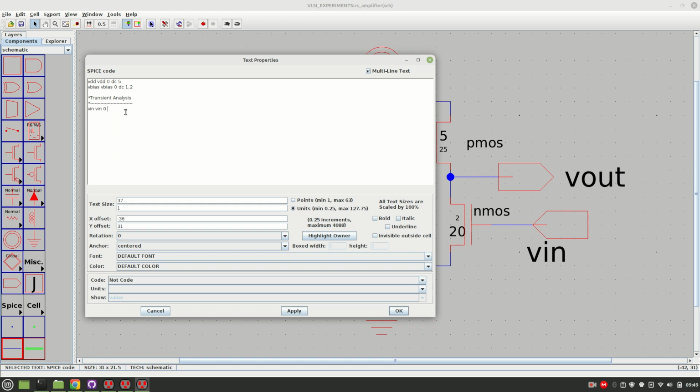Okay, so a small AC voltage we will give in this amplifier, so we can see exactly how the waveform is, a sine wave we are going to give. So V in, this is the same syntax, 0 and sin.